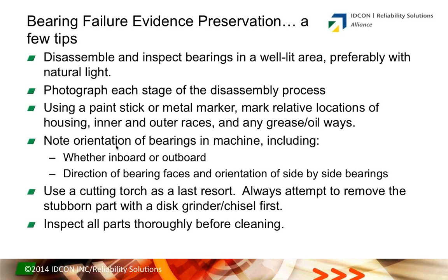Another thing I encourage is, as we're disassembling our bearings and cutting them in half and inspecting them, photograph the process or video it. Obviously I do a lot of this myself, and I'm in a root cause mode. I've got my Sherlock Holmes hat on and the big pipe and everything, and I'm looking at this bearing thinking what could be going on and listing possible causes.